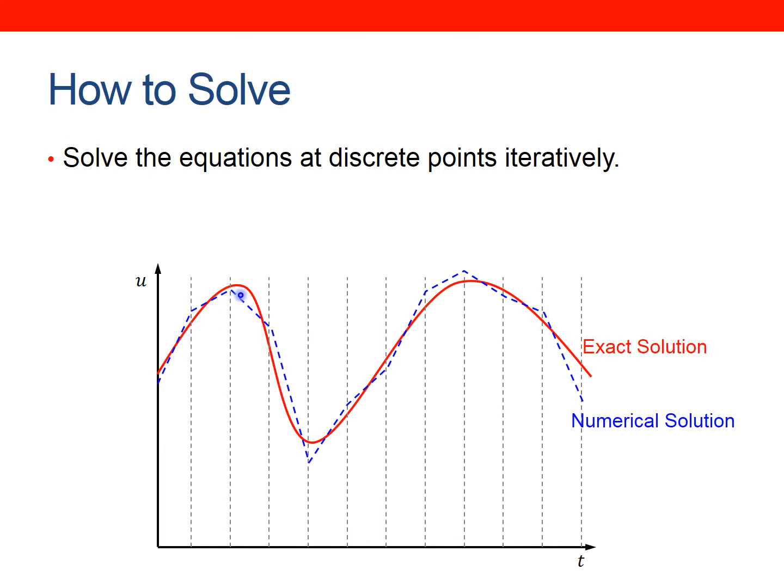So we're not getting the exact solutions, and what I've tried to do on here, which might not be that obvious, is that where you do, for example, here, see that this velocity is changing quite quickly with time, that's where, if your time step is too large, you're going to miss information, because you won't be able to capture that fast rate of change with time.